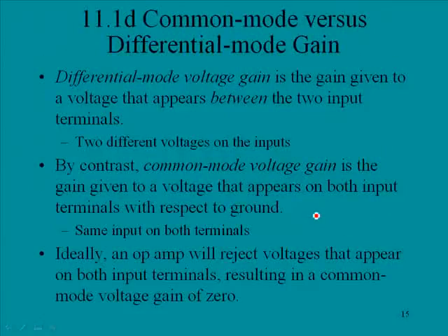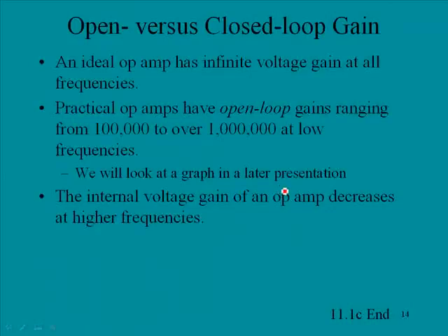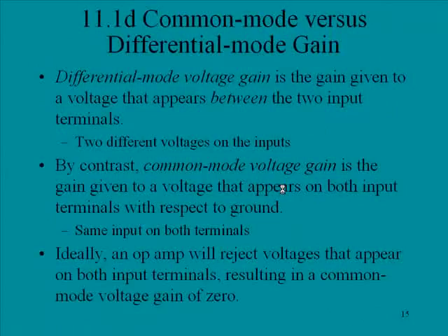We also looked at common mode versus differential mode gain, and we recalled that with differential mode gain, the op-amp amplifies the difference, and with common mode, it hopefully didn't amplify anything, because if you have the same input on both inputs, you won't get an output with an op-amp. Okay, this concludes section 11.1.